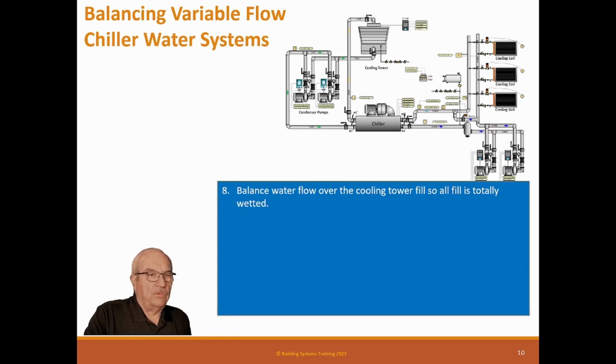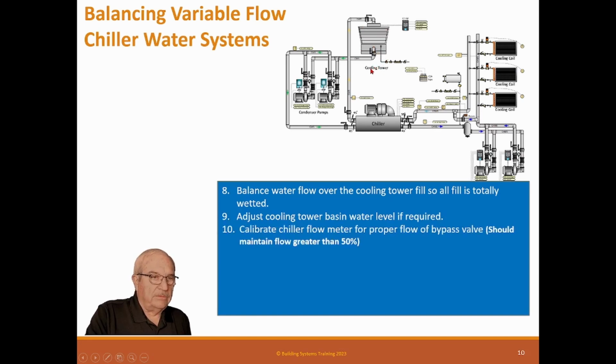Balance the water flow over the cooling tower, the same thing. You need to make sure the fill is wetted by adjusting the pans out there, and you need to set the water basin just like we did on the last one. Adjust the cooling tower basin for water level.